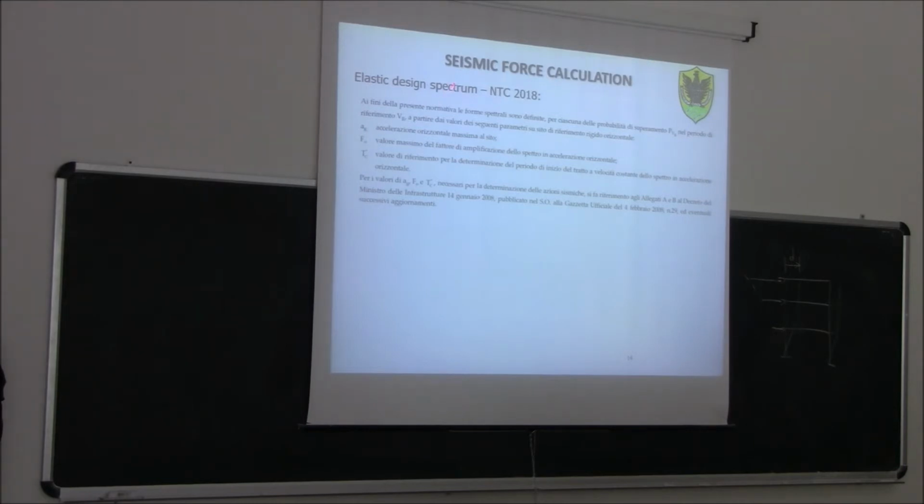So, elastic design spectrum. Now, of course, when it comes to calculating the elastic forces, we need to take the regulation, either the Eurocode 8 or, if you are in Italy, of course, the Italian regulation. We can also use, as I told you before, the Eurocode 8, but with a national application document, which is based on these values that we can find in our technical Italian regulation. So, as you already know, we need to take these three values here: the maximum horizontal acceleration, the maximum amplification factor of the spectrum, and this value of the vibration period, which is on the boundary of the constant velocity part of the spectrum. So, we need to make some assumption for this value.